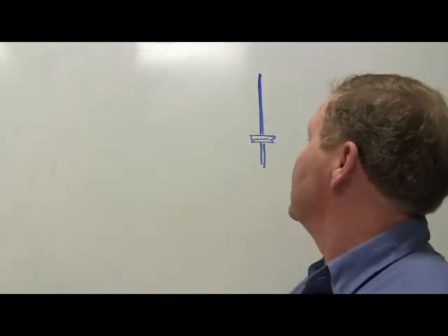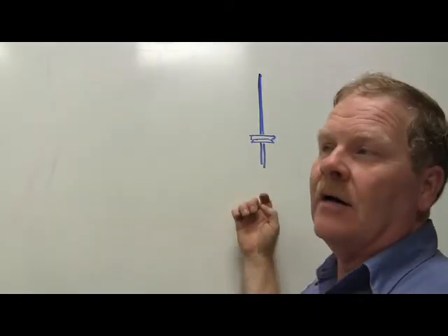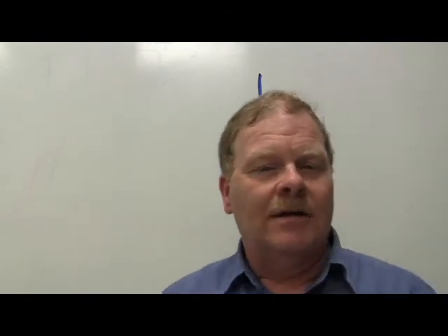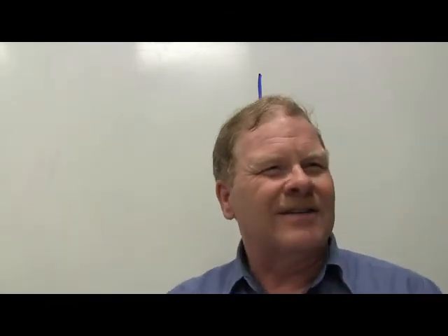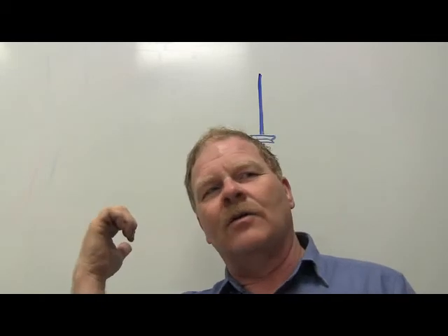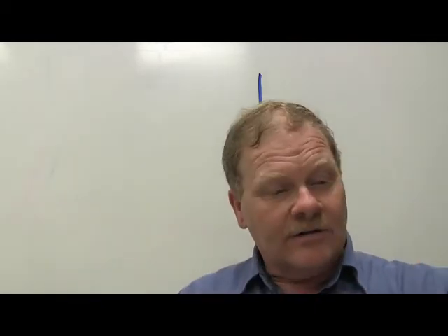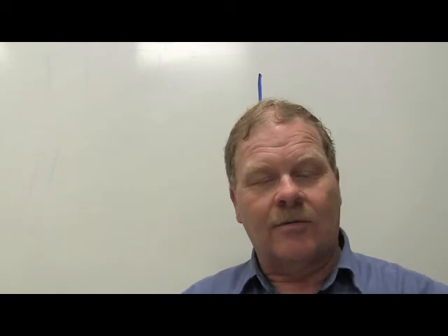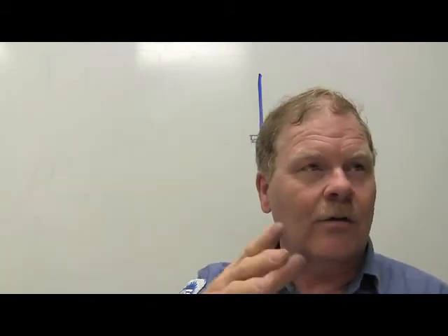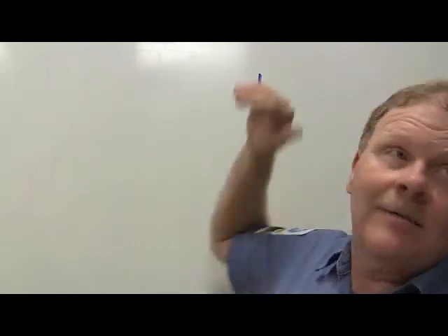What you're going to find out is that if whatever you're looking for is on this side of the grommet, it's in the engine compartment. Like if it's the power distribution center feeding something on the inside of the truck, if you see them grommets there and where the origin is out here in the engine compartment, don't look out there for what you're looking for. If it's on the other side of these grommets, it's going to be inside. That's really important to know too.